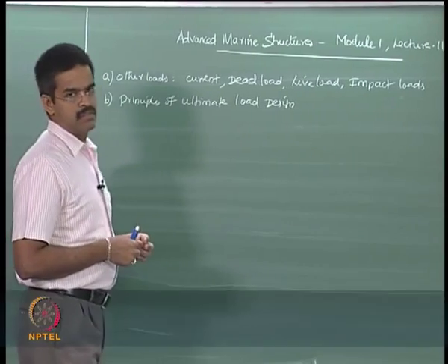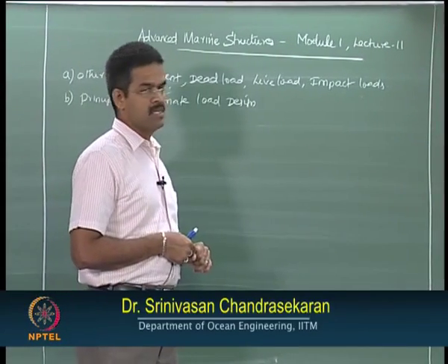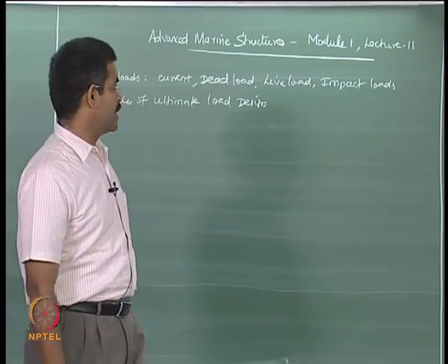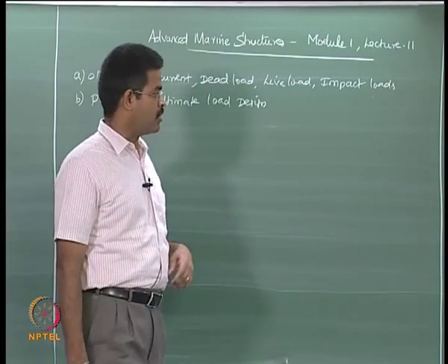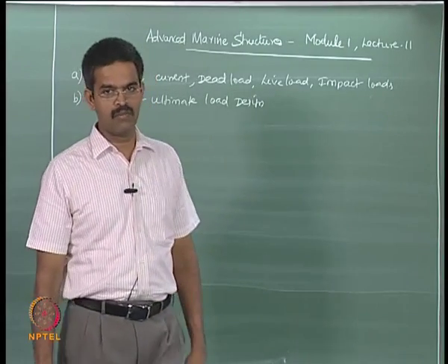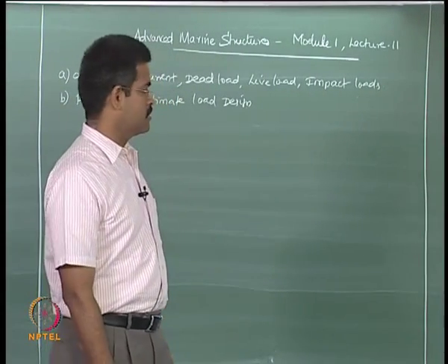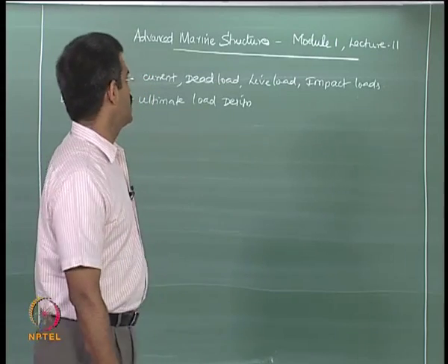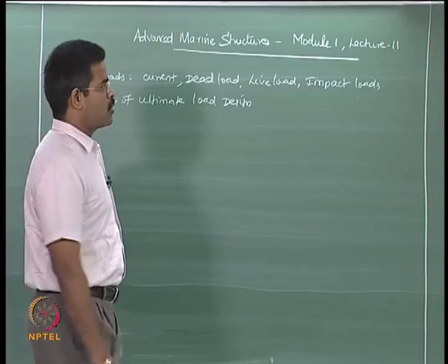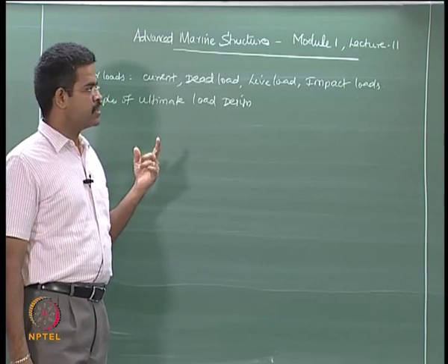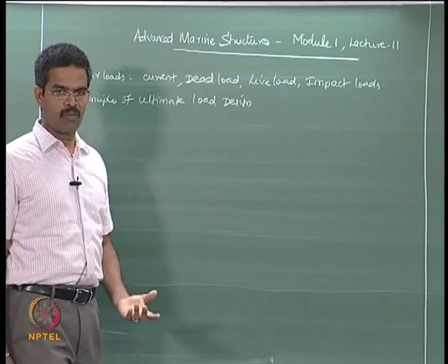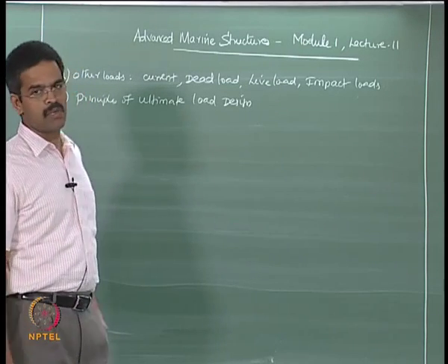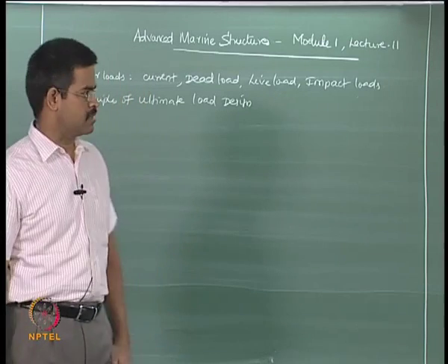In the last series of lectures, we discussed different kinds of marine structures: bottom founded or bottom supported, flexible systems, and new generation structures where form governs the functional design. Subsequently, we discussed the environmental loads acting on marine structures. We discussed in detail the hydrodynamic loading, wind loads, and seismic loads, earthquake loads, acting on marine structures.